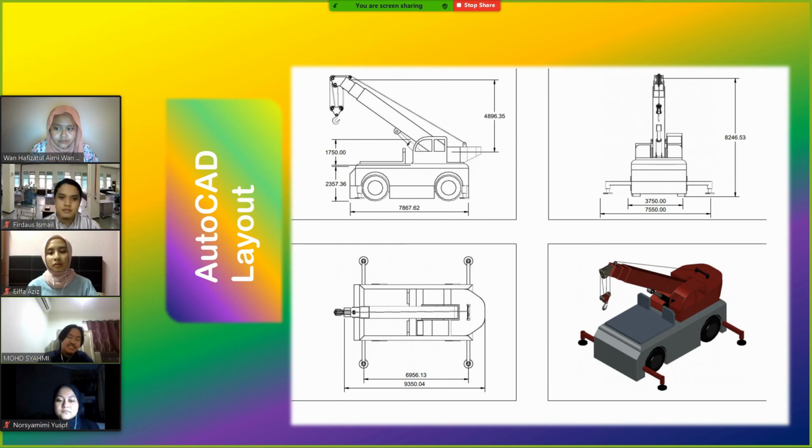On the other hand, if we are comparing the trapezoidal cross-section hook with the I cross-section hook, the I cross-section hook type is much better in absorbing the load. However, to manufacture the I cross-section hook needs more machines, and waste of material is higher at the end of the manufacturing. That's why we are choosing the trapezoidal section type.